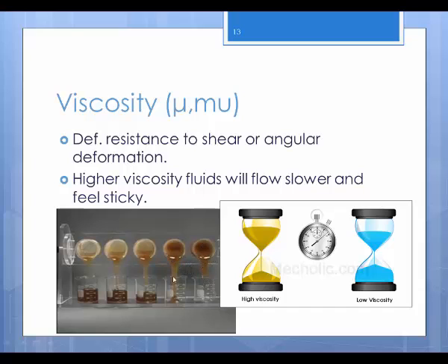The streams themselves look different, and this is indicating the way that the fluid shears between itself, even if there's not a container touching it. If it was just flowing out in the open like in space, its viscosity would still matter because it's not just a measure of resistance to flow against a solid boundary, it's resistance to flow amongst itself too.